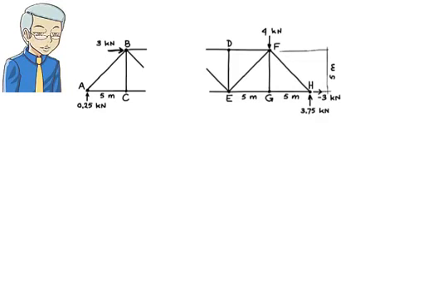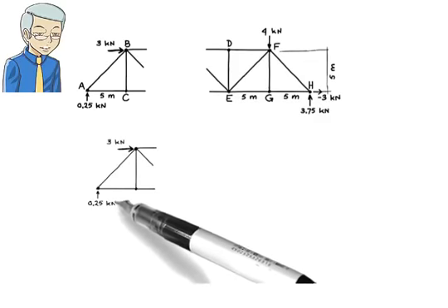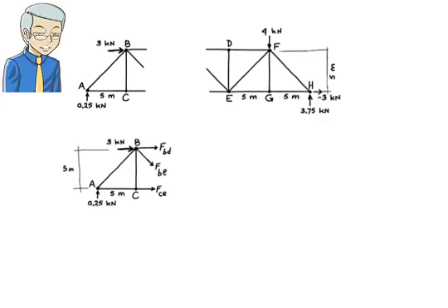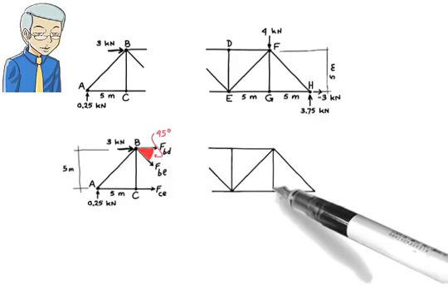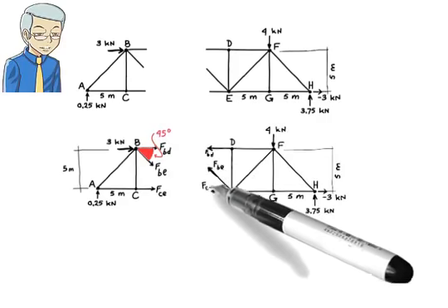When we cut a truss into two parts, we must show the internal axial force in each cut member in the free body diagram. Here, since we have cut through members BD, BE and CE, we need to show the axial force for each of these members in both the left and the right substructures. So, for the left substructure, the forces are drawn like this. For the right substructure, they are drawn like this.